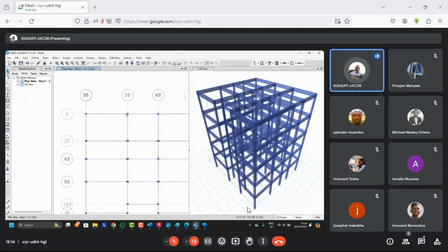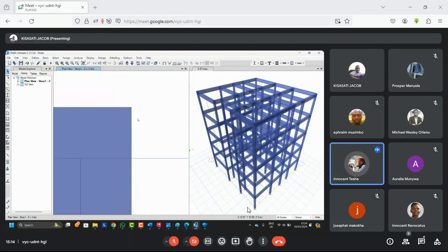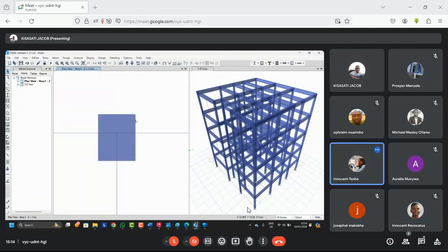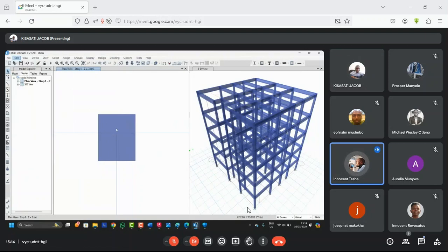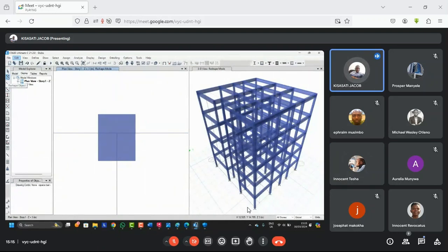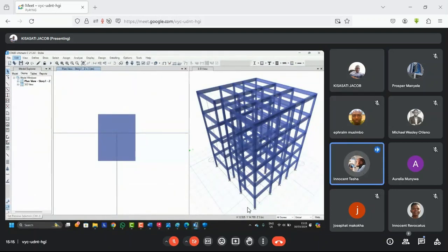Now, engineer, please tell me the point because you had a very good point. I was saying that the node selection cursor was not active. So how do I do it? Below File, there are two cursors. Do not click File. Just go to the icon which resembles this cursor, on your left side. That one. Is that not the node selection cursor? No. This one is reshape object. Then this one is select object. Oh, I thought it was used to select the nodes.